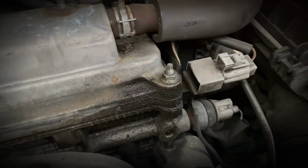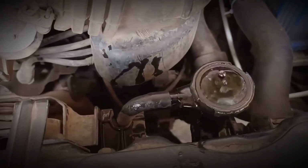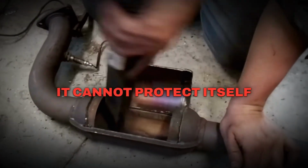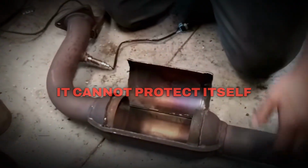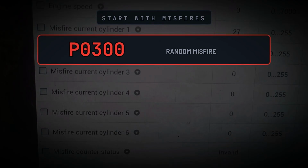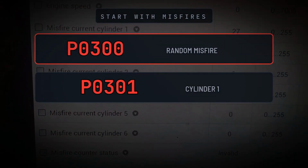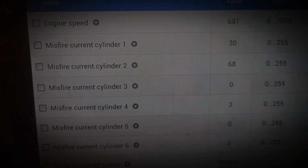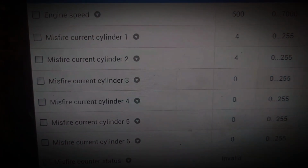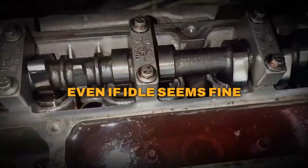Check 3. Check the engine before the converter. A catalytic converter processes the gases produced by the engine. It cannot protect itself from a continuing combustion problem. Start with misfires. Check for P0300 and cylinder-specific codes such as P0301 through P0308. Do not look only at current codes. Some scan tools can display misfire counters or history even when the engine appears to idle normally.